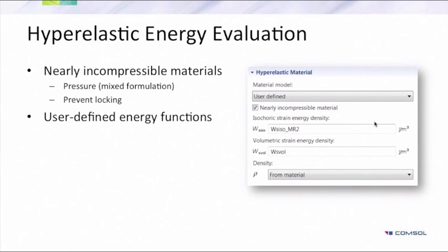For the hyperelastic materials, we have the nearly incompressible option. Then you can separate the energy function into two contributions. One is isochoric and one is volumetric. This prevents locking when you come to the nearly incompressible situation. And the functions can be defined as a function of any variables which you can calculate in COMSOL.